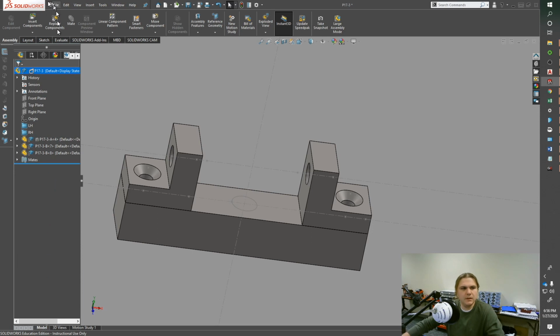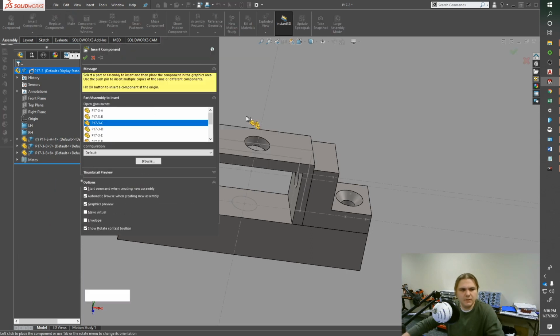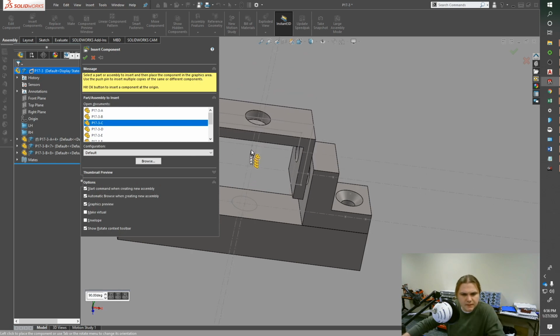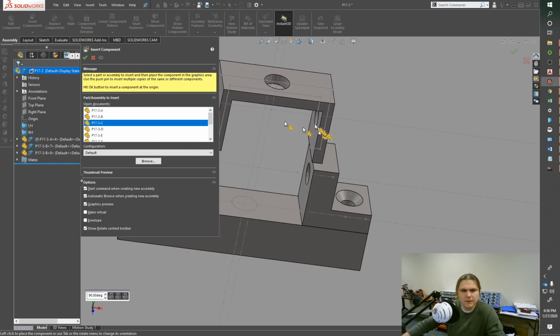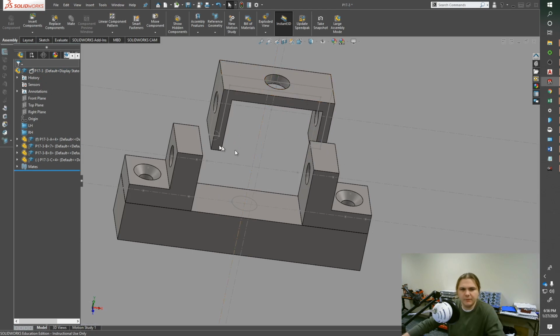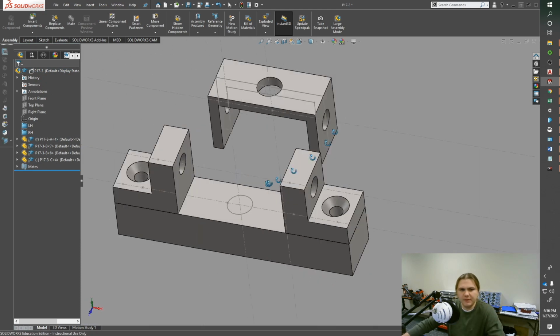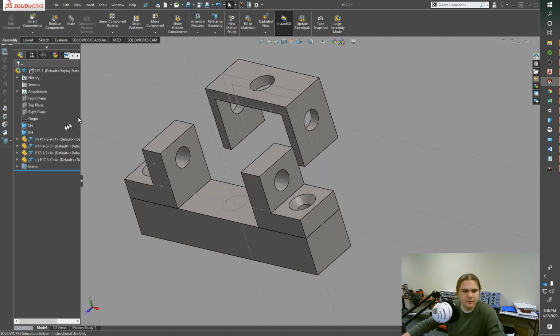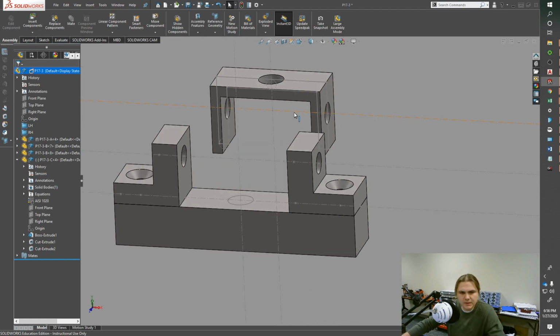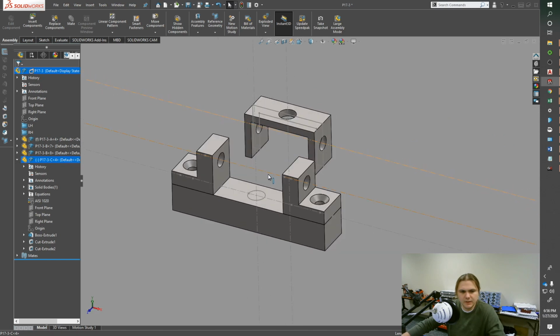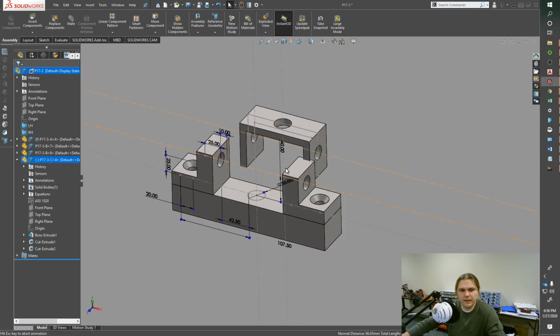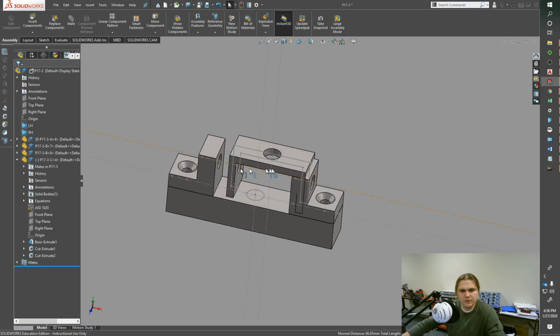I'm going to put in another component. It was snapping there. I'd be a little cautious with letting things snap without knowing exactly what they're going to. So just plopping it in out in the middle of nowhere will reduce the chance of accidentally doing something you didn't intend. So I'm going to do this line I threw into this part, coincident to the line of the layout. And then I could do right to right, or I could do the lines again. So select this one, that, and coincident. And now that guy is fully constrained.